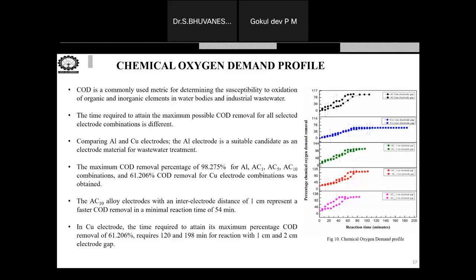We should know the toxicity. The sludge we have after this particular process is going to have aluminium in it, it is going to have copper in it. What may be the toxicity? If it is having high toxicity, then we can't dispose it anywhere. In that case, at least we can convert it into some other product, like composite brick or some fertilizer.